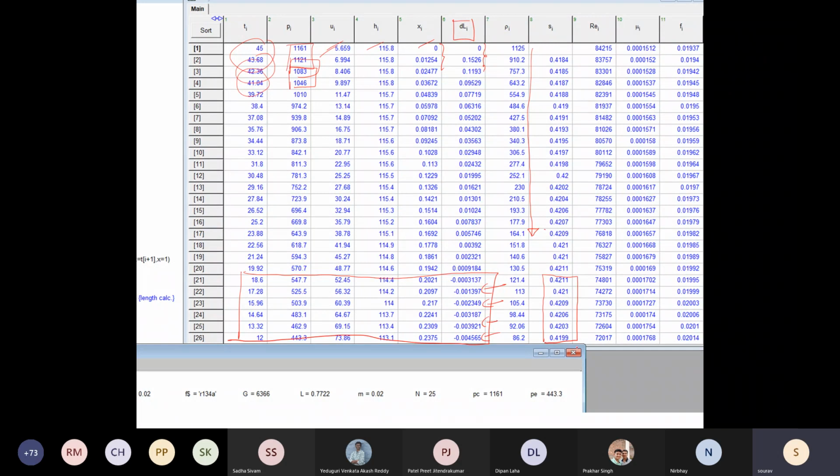You expect the specific entropy of the refrigerant to increase during a throttling process. But here what I am seeing is the entropy is decreasing. So this portion of the calculation clearly shows that this part is not possible.